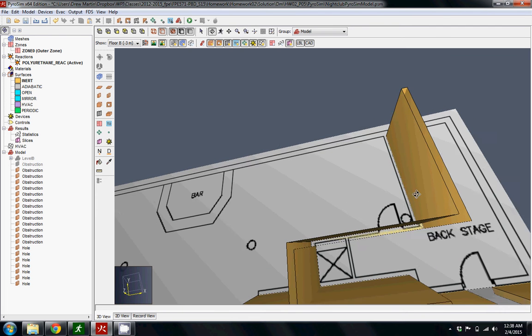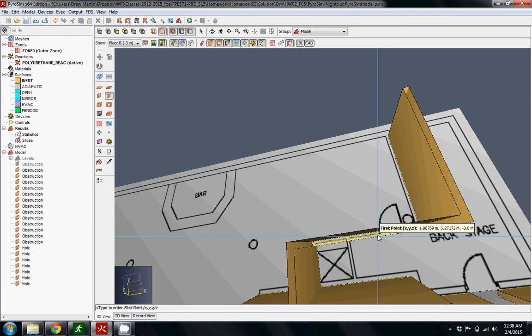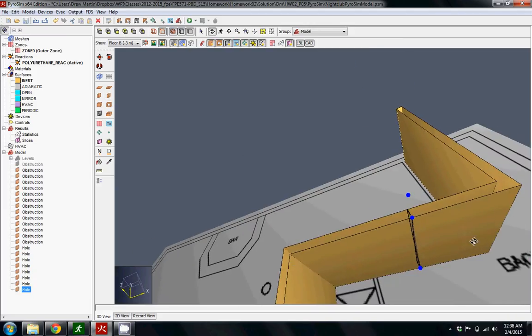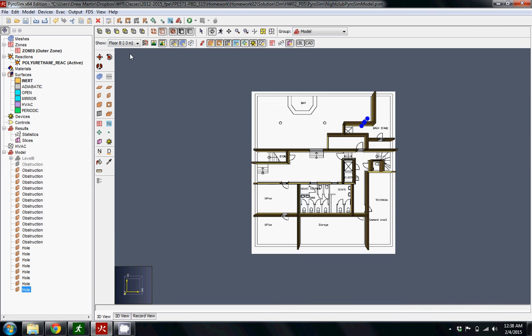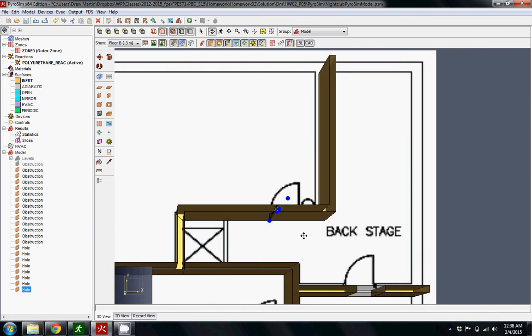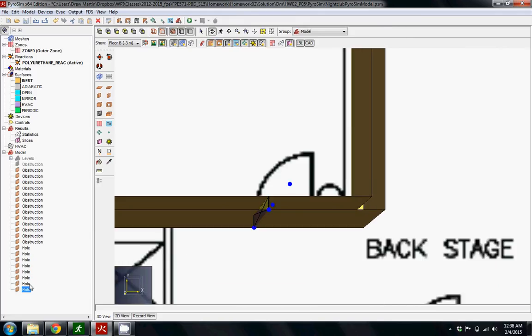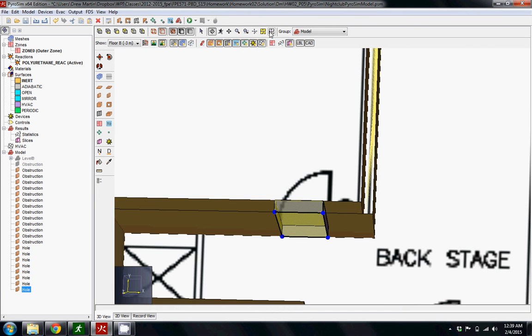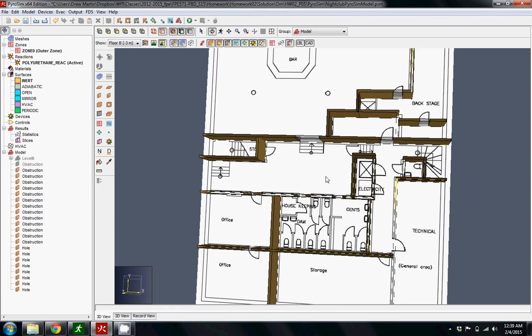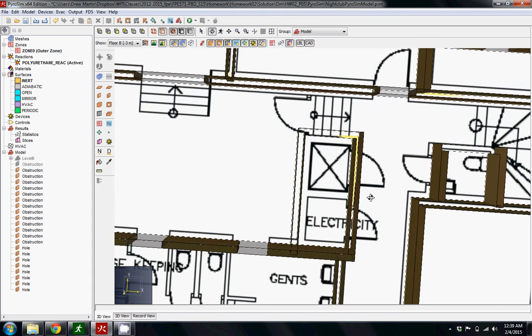And so then we have another doorway up here. Again, make sure that you're on an even plane and that you're actually snapping. You can kind of feel it tugging at the bottom of the wall here. So when you're drawing, just make sure that you're snapped to the right location so you can draw everything squarely. Otherwise, it can get a little squirrely, like we've seen a little bit.